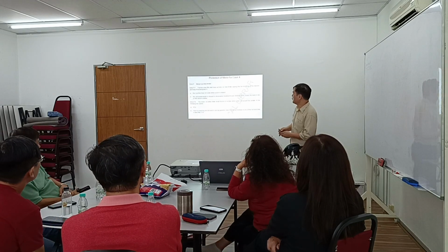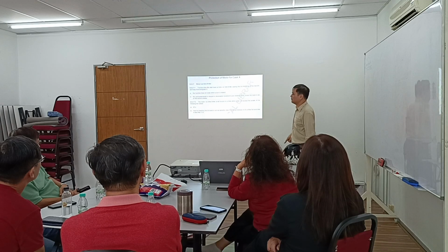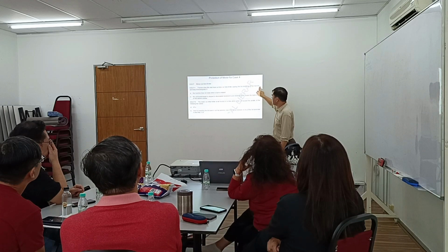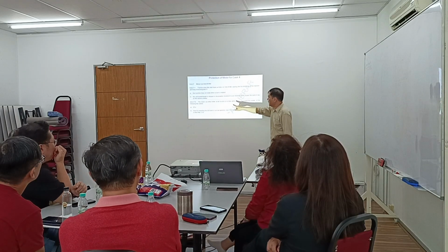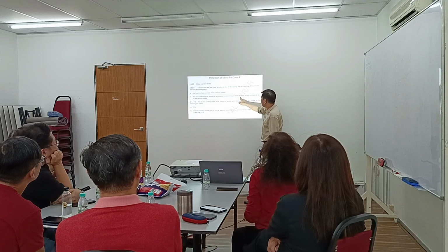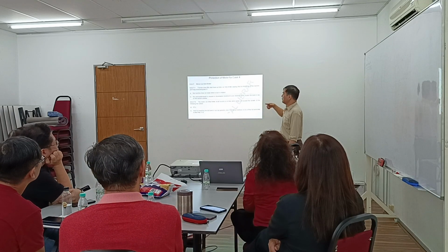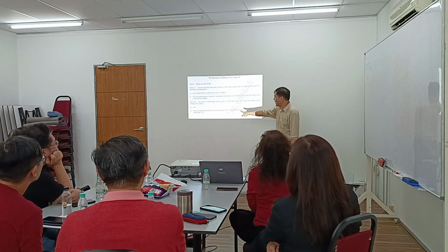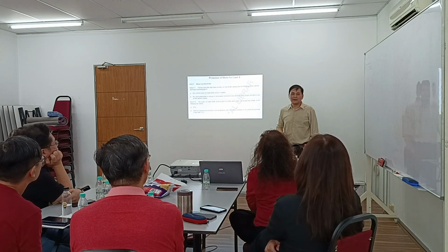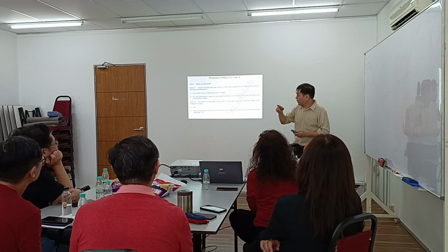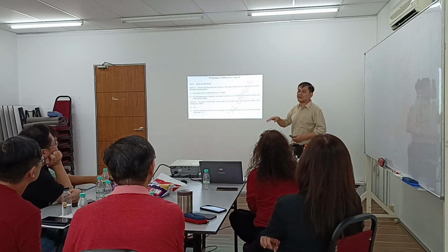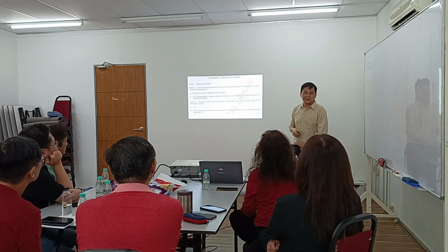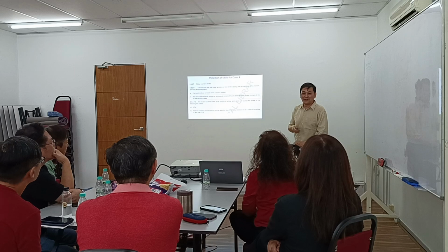How? So we have the motor runtime limiter. A traction lift shall have a motor runtime limiter causing de-energizing of the machine and keeping it de-energized. If the counterweight is caught at the downward movement by an obstruction causing the rope to slip, then after a certain time, 45 seconds, or the time for traveling the full travel plus 10 seconds, it will cut off the supply. So it keeps the people in the lift car safe. Okay, you follow?